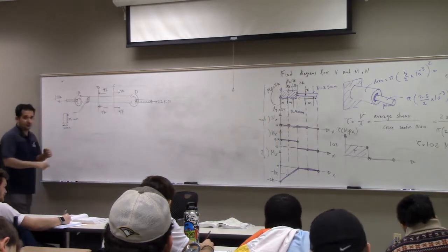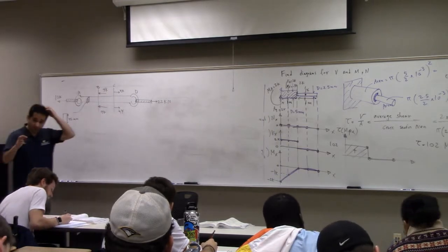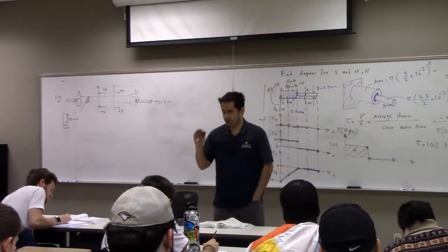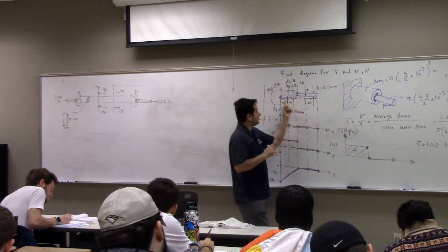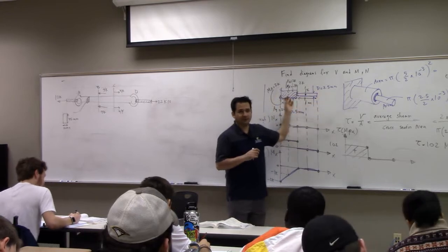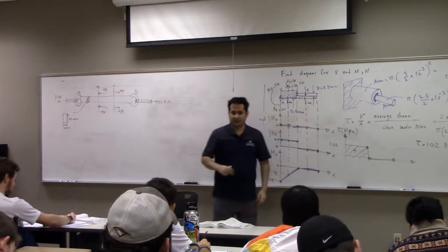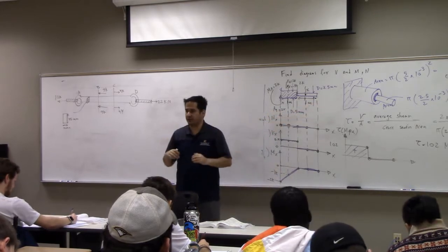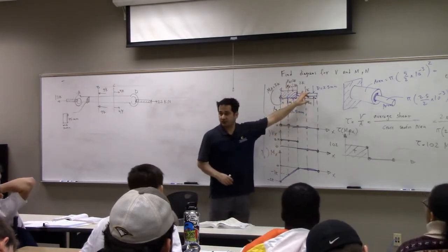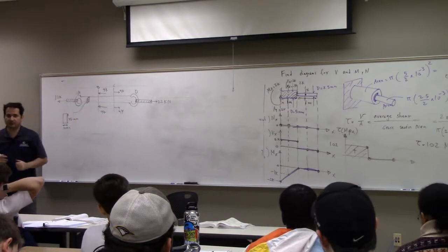Once you get axial load, then you divide at each section by its local area, and then you get the normal stress. Don't forget, sometimes these two curves are different, the axial load and normal stress diagram. For example, if you have just one normal force here, but you have a cross-section change, the axial load is constant, N is constant. But what about the normal stress in this curve? You're going to have a jump because the area will change, right? So these two curves are not necessarily just simple scaling. They may have some sort of variation to it.